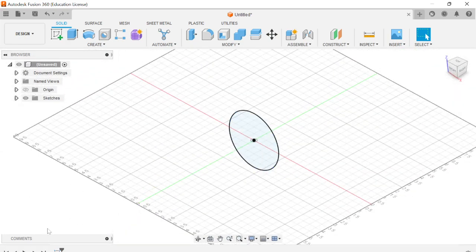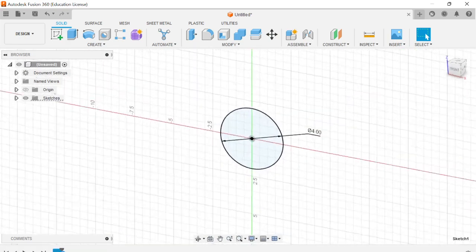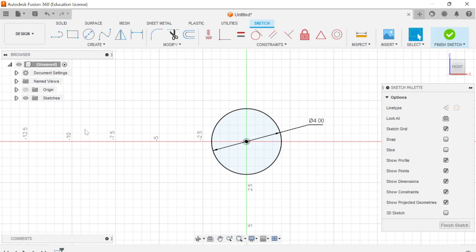We'll zoom out. It looks good. And I'm gonna go back, and I'm gonna reopen the sketch, and I'm gonna make one of the teeth, and then I'm gonna pattern it around the body of the gear. So I'm gonna start with the line tool, and I'm gonna go use the construction feature, right? This is a personal favorite feature of mine. I use it all the time. It's super great, and it allows you to kind of eloquently model your things without a lot of busyness on your screen.